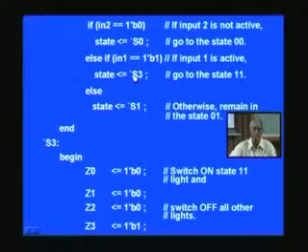It will go only at the next clock edge. It only prepares the ground to go for the next clock, right here. This will become very clear to you if you see the timing diagram while we simulate the whole thing. And finally, we use one else, because all the conditions that we want to meet have already been met here. So whatever doesn't meet, is actually in1 is 1 here, in2 remember is 1 here, and in1 is 0 here, then only it will come to this state automatically, because the other state is taken care of here. So the only state that remains is in1 is 0, which will naturally take it to S1.